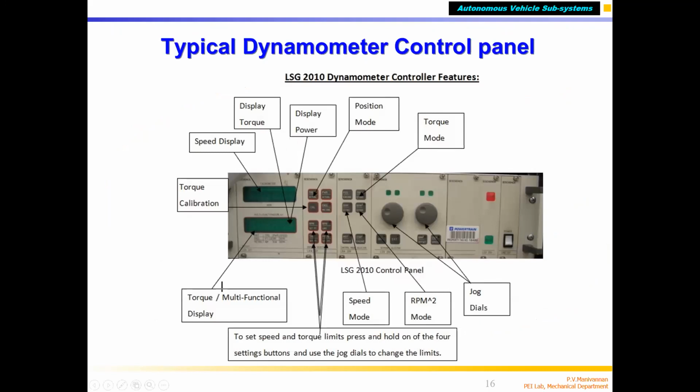If you want to control air fuel closely, you need to measure the actual air fuel ratio. For that, you have to use the lambda sensor, which is called the EGO sensor. That is for closed loop control. We will talk about it in the next class. Okay, sir. Thank you.